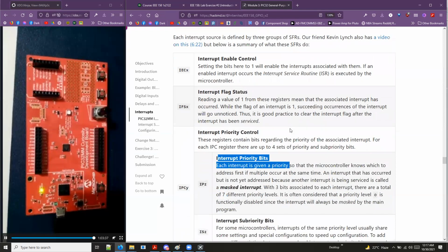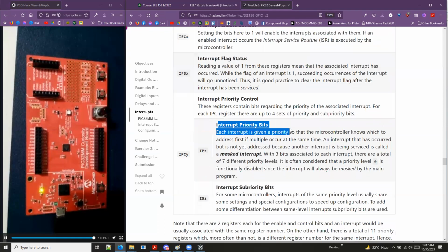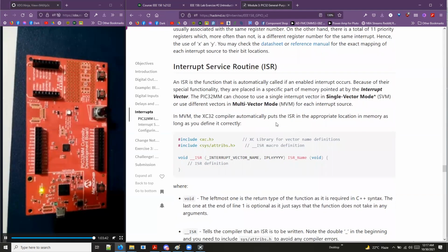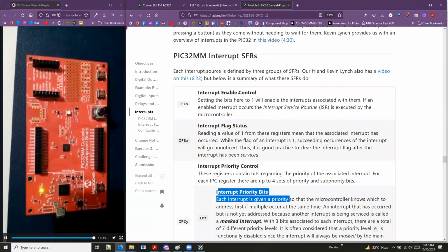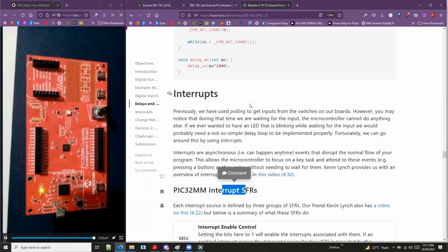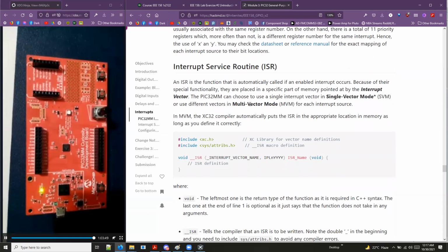Then, the major thing about interrupts is what we call the interrupt service routine. Whenever an interrupt occurs, our program stops itself and goes to the ISR. For example, we have a loop of our main code here. It just runs, going around and around. Our ISR is stored in a part of memory. So, our program is running and then an interrupt comes in.